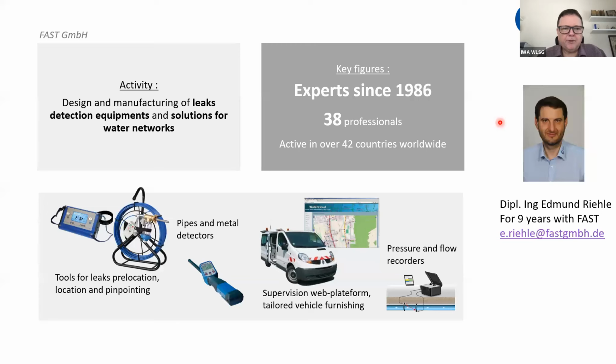And we have another one from Eric, which is, why didn't acoustic method correlation work? What is the pipe material? The pipe material, this is another difficult thing, is GRE, glass fiber reinforced epoxy, which is widely used even in freshwater in the UAE. And this propagates the leak sound not very sufficiently as well.